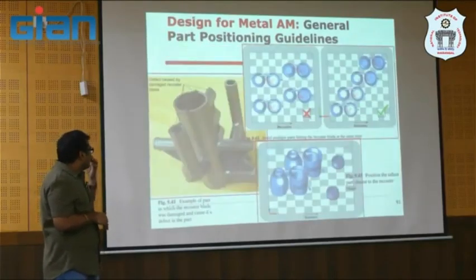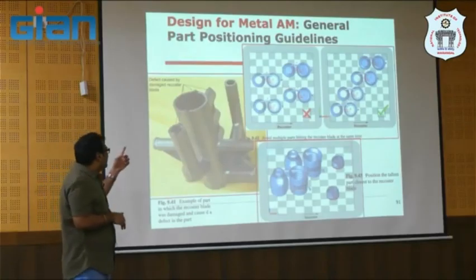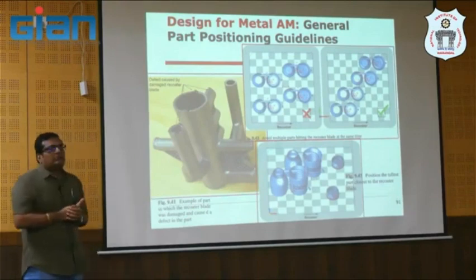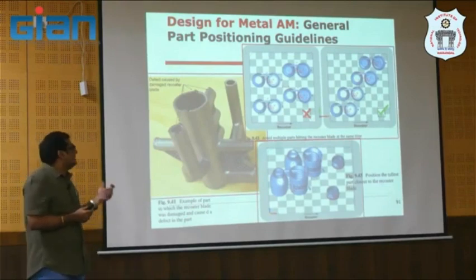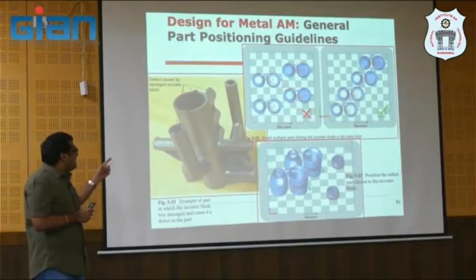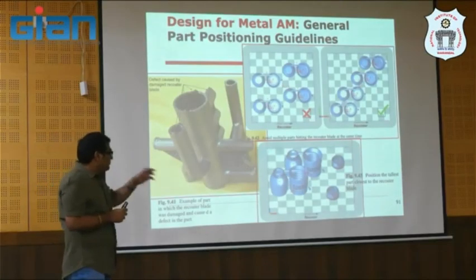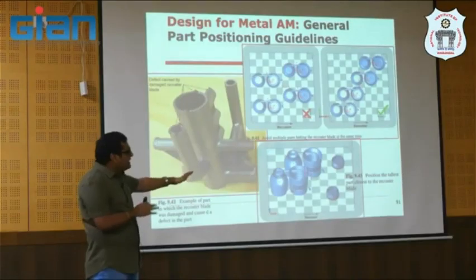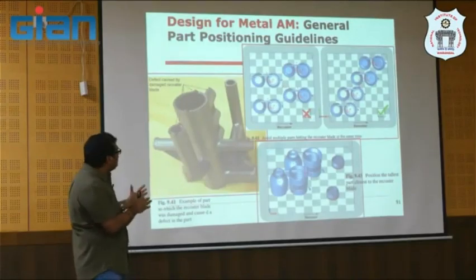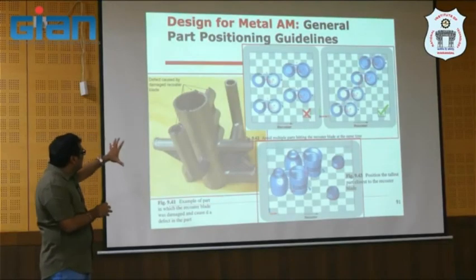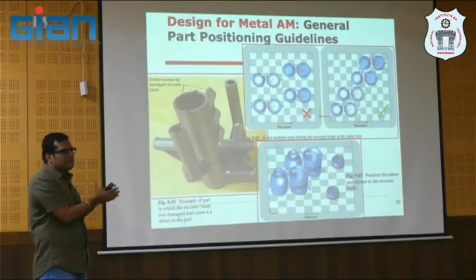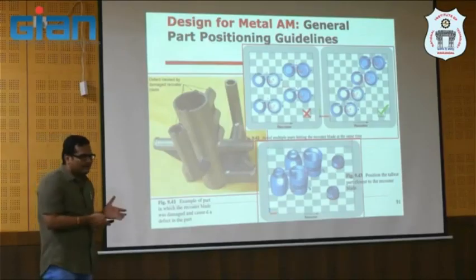And another thing is that sometimes the recoater blade will hit your parts, right? Then the recoater will badly damage your part, which we need to take care of. And what could be the tallest part in your build, all that we need to consider, right? If you consider all that, you may not end up damaging your printer or damaging your part.